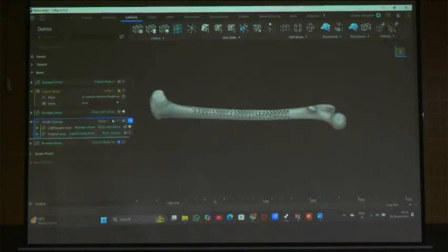I took a bracket, applied topology optimization, applied lattice structures, and combined both. You asked about the gradient, right? There I also applied both uniform as well as gradient lattice structures. I just wanted to explore the potential of these methods and how much weight they reduce.